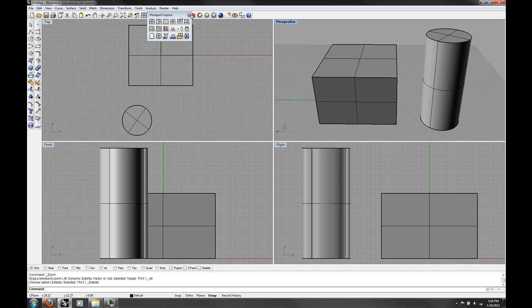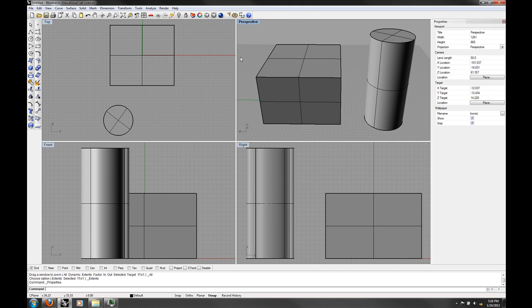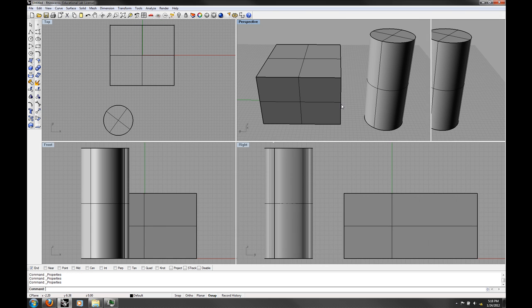Okay, so back to what I was talking about. When you open the program up, you might see something like this, but it's very useful to have the layers panel and the properties panel. The properties panel is accessed by pressing F3. Okay, you can press F3 and it pops up. You can close it with a little X there. Okay, F3.